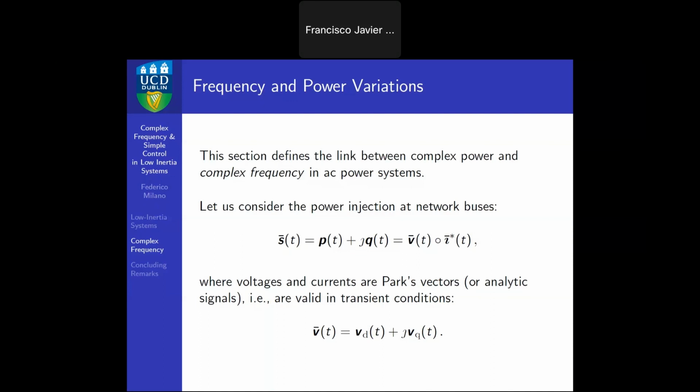It's not the dynamic phasor that is defined in some papers, because if the model is taking into account electromagnetic dynamics, we still define just this vector. So Park, in principle, retains all the dynamics of the system. It's just a transformation. Park is defined starting from EMT quantities in reality.